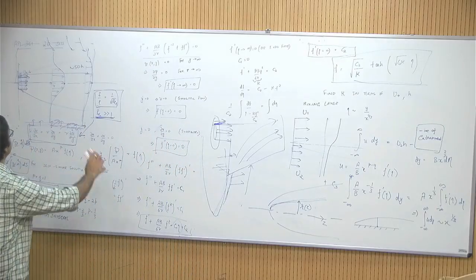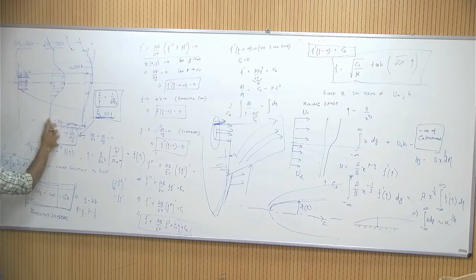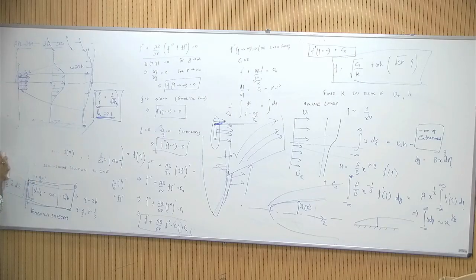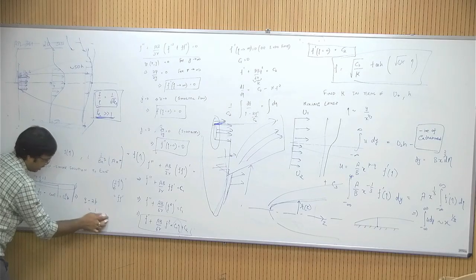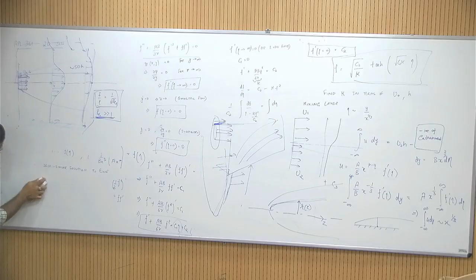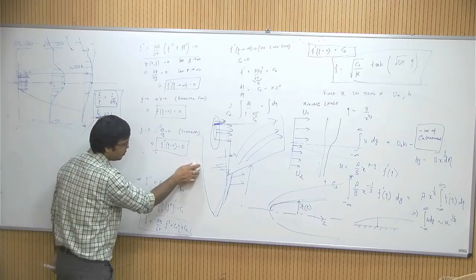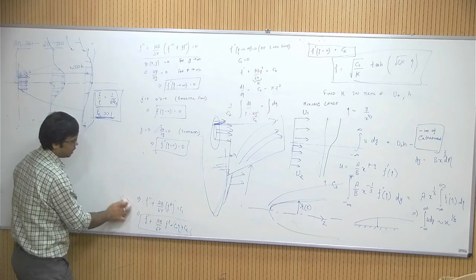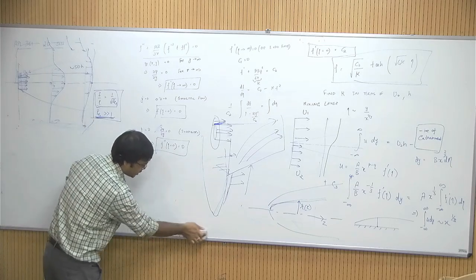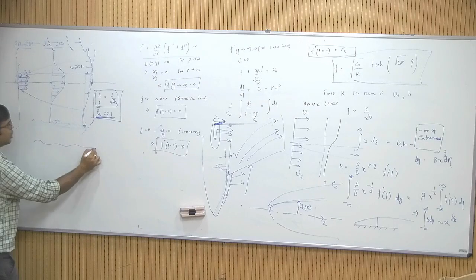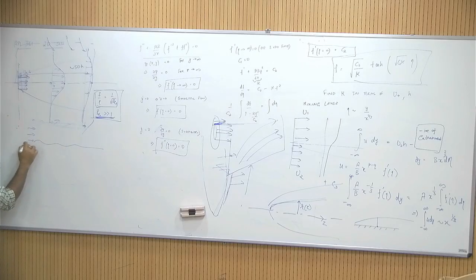Now, before closing this discussion, I wanted to give you some basics. So, what is the practical use of boundary layer theory? We started formulating this because we were not satisfied by our high Reynolds number flow equation, which gave us the inviscid equation, and then the inviscid equation said that there is no drag. If you remember our inviscid flow past a wavy wall, if you go back to the solution, we said that there is no drag on this wavy wall.